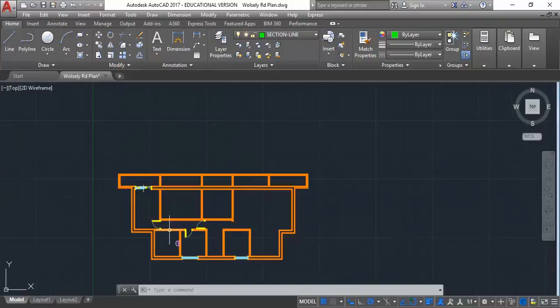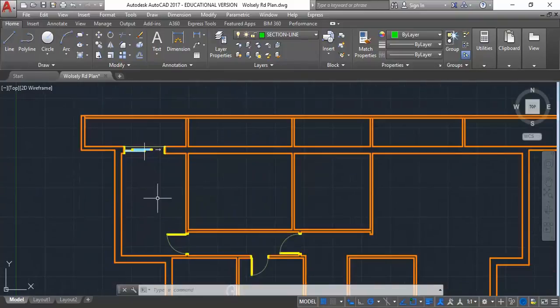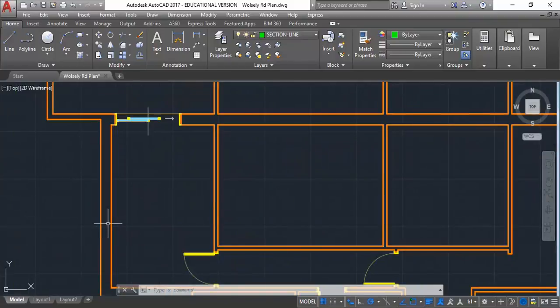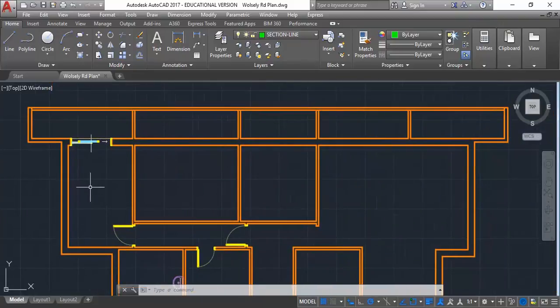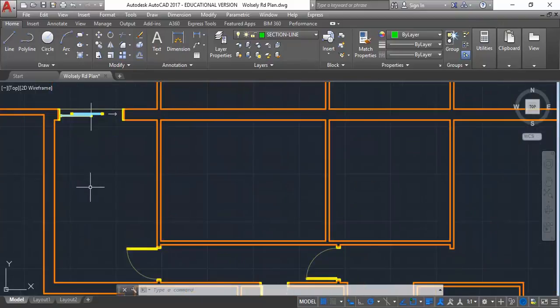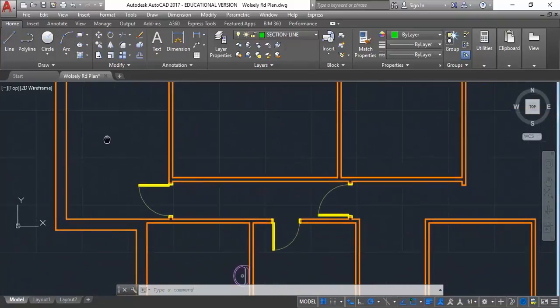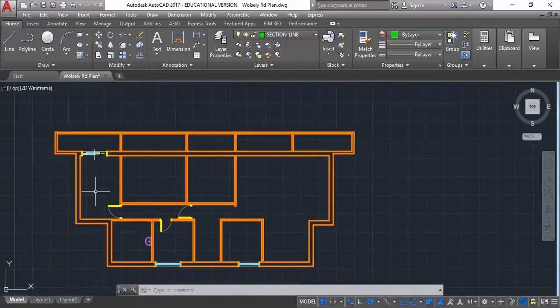Yeah, all the walls should be hatched in. So if you're dividing the exterior and the interior walls up, that's good practice for new walls, so anything that you're adding as part of your design. When you're drawing, say you have a hatch in the wall, but say the back wall, you draw that up and you draw the interior wall, it looks like that in the drawing, but if you hatch them, it's going to look like a thick. You only hatch the walls that have been cut. So not all the walls. Some of the walls won't be being cut. They'll be in elevation. But it'll be a lot clearer, you'll see, once I've drawn it.